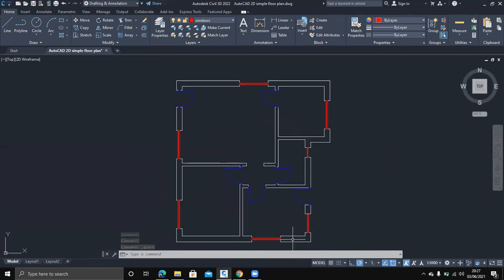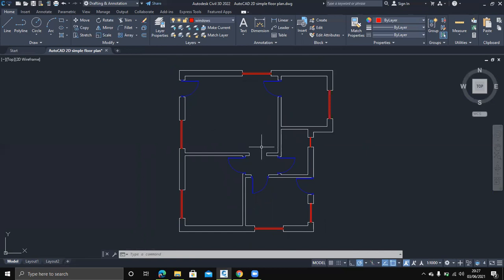Okay, so once I have created the windows and the doors and the floor plan, the next thing I need to do now is to insert some texts. And then I will use single line text first. You guys remember how we were doing single line text. You specify the first point, the height of the text, and the next is the direction of the text. So that text actually is living room, okay? So it is living room, and you can see it is very big.